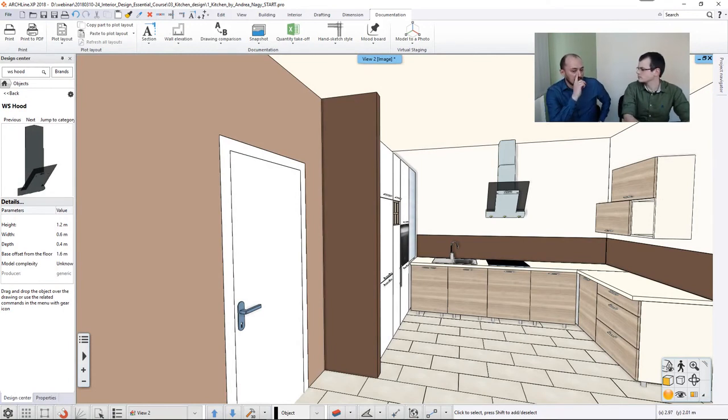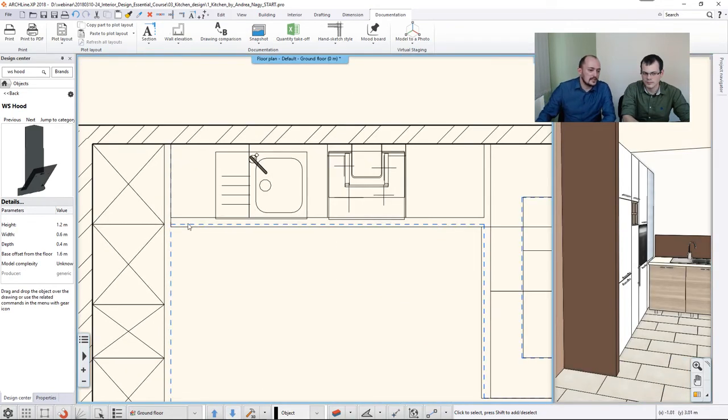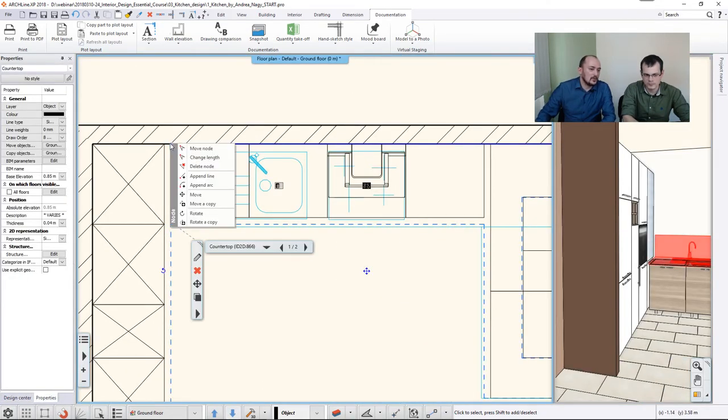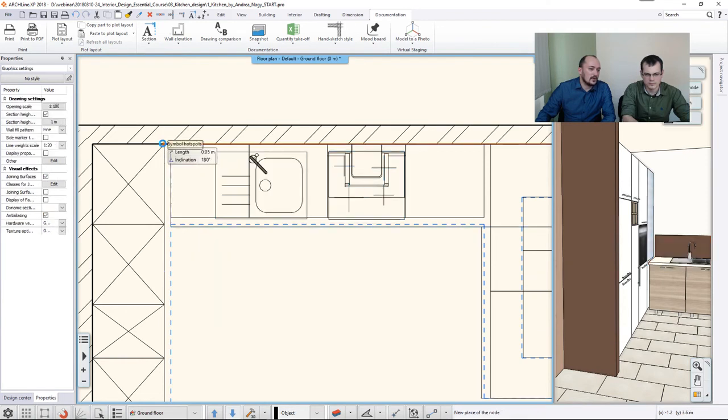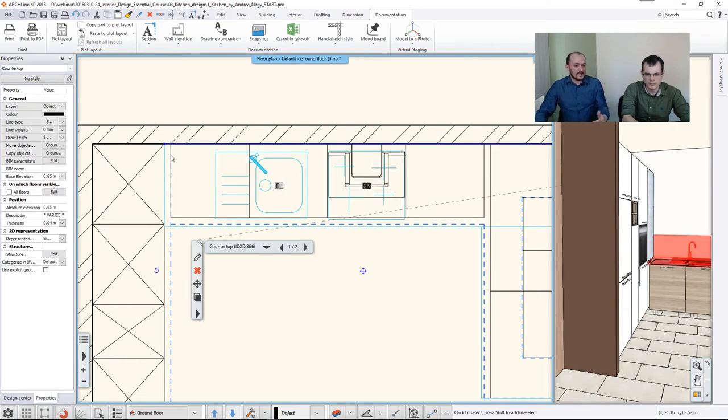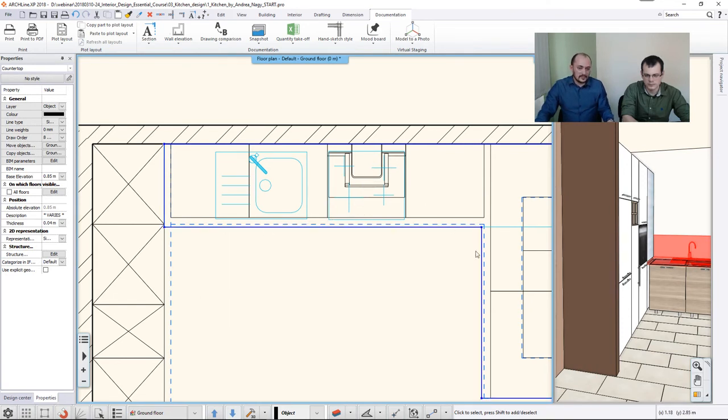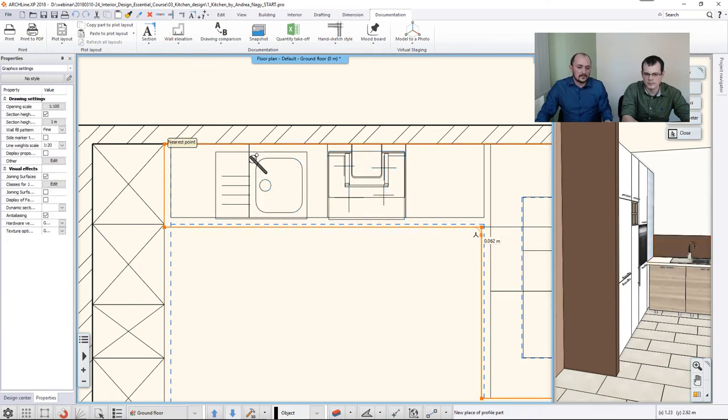And before I continue to load this final stage, let me show you one more thing, because I actually did not talk about that. When you design a worktop, you can still select it and go and select its edge and make it longer, for example. The same way, you can click on the unit and use this component mode, and then you can reach all the edges. You can do something like this. You can even round it off like that.